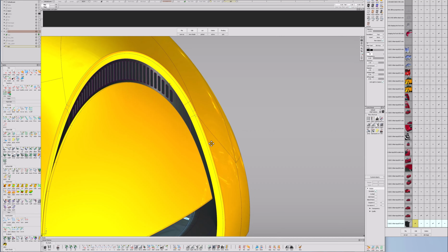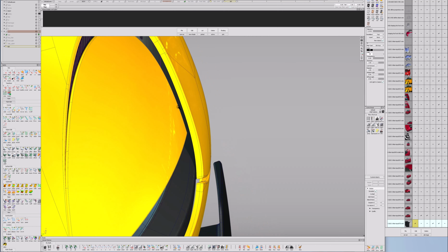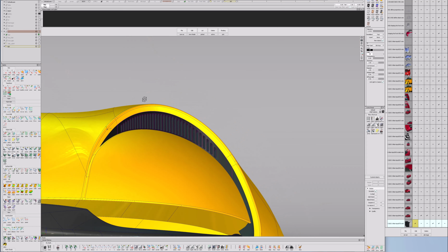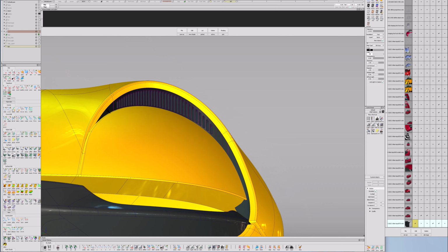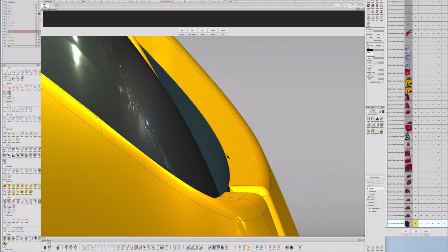I always try to go with small flanges, but then, for example, if you want to put a radius on this edge, so the black plastic part has the fillet and the yellow part has the fillet, it will not work at this angle. So you actually have to add thickness for the black plastic here. But yeah, I decided not to do it.